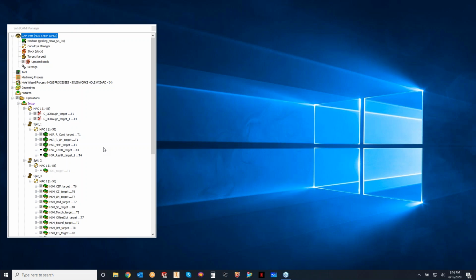It's limited in that you can't choose some of the geometries, but a lot of the stuff you're going to change on the fly on the shop floor doesn't even need that geometry. That's one benefit of it, in addition to the fact that you can still do simulations. That's pretty good in itself, because normally when you make hand edits, you don't get to see the results. But when you make a change, say you've added a proper clearance to the holder or a fixture collision detection clearance, you can see what effect it has inside, let's say, Solid Verify, on your low-grade computer.